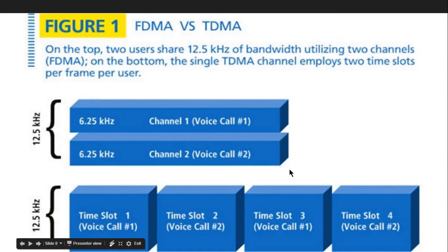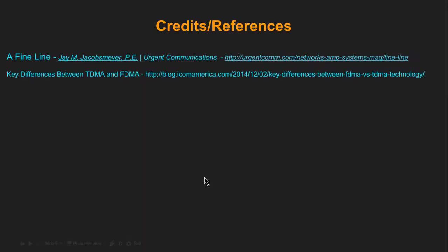It gets beneficial when you are able to stack multiple agencies in public safety, at least in the same bandwidth. You can get two agencies in the same bandwidth, same frequency that you are licensed for, whereas here you're using the same bandwidth, but you're only getting one slot. You're taking one slot. It's a wider bandwidth signal. Hope that didn't confuse anybody.